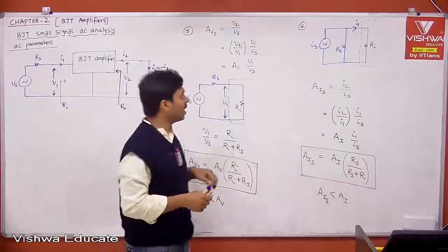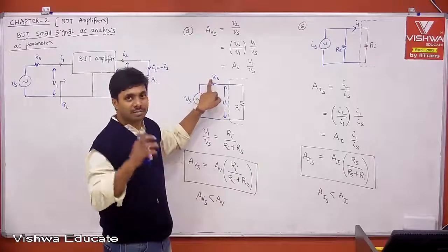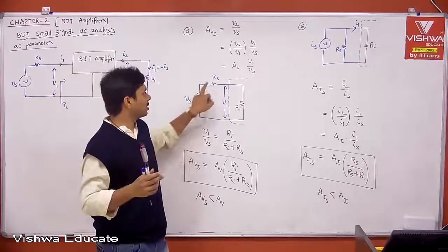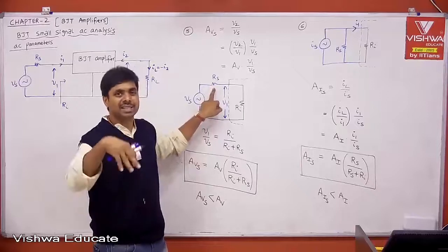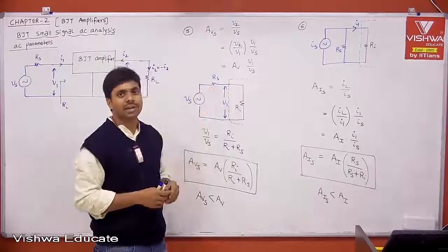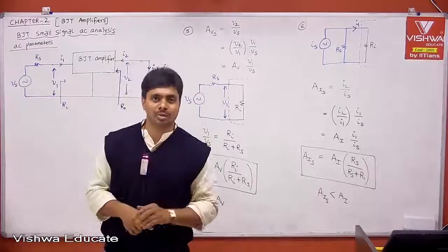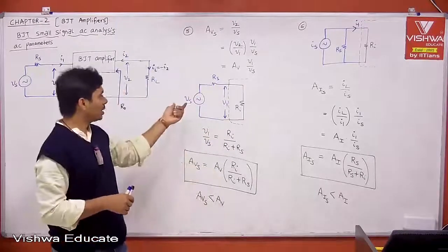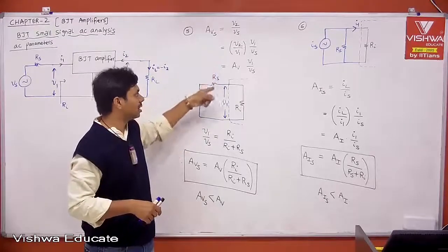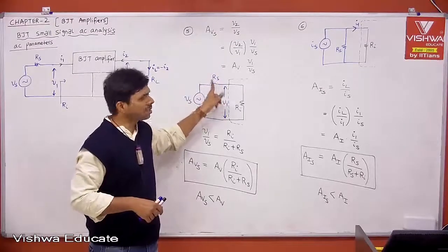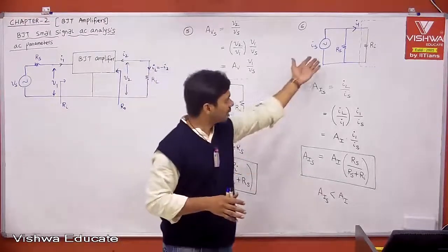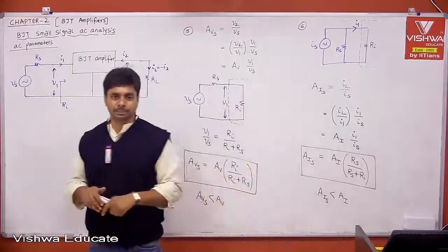Strictly speaking, we should define it with a small rs, because according to the analysis we did before, this is the voltage source resistance; we should call it internal resistance, equivalent resistance, dynamic resistance, right? That is nothing but this only. We represent the equivalent in series with the ideal voltage source, and the actual resistance is represented in series like this. Strictly speaking, that is nothing but the dynamic resistance, and remember that it is the dynamic resistance in the case of a current source also. Okay.